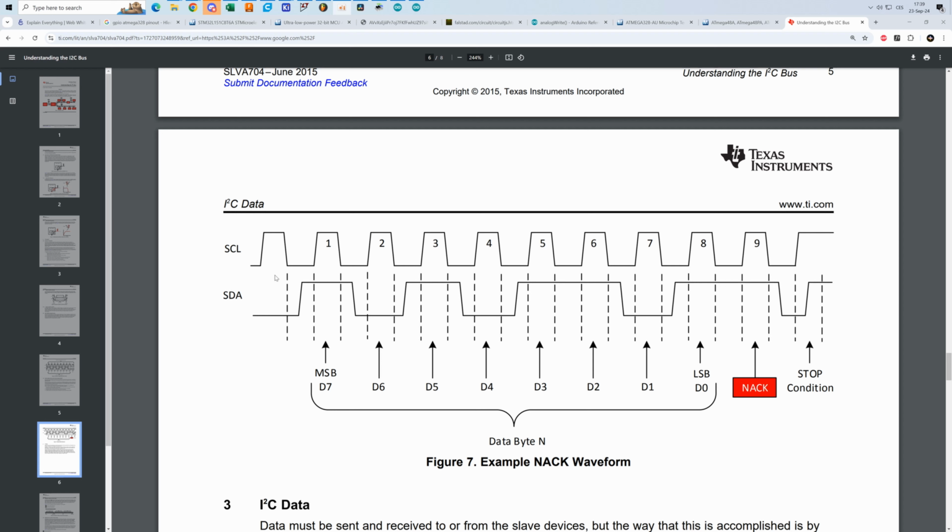So you can see when the serial clock turns to logic 1, it turns high. Then here we have serial data turned on. What that means is that the device, or the microprocessor, is going to look at the rising edge of this clock and it will see that the serial data is logic 1.